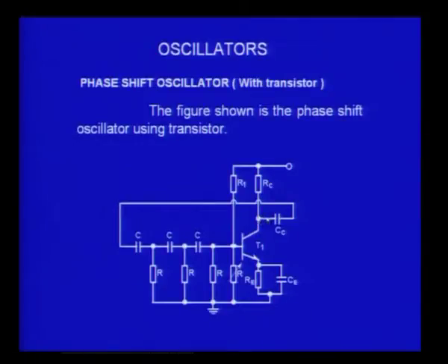Now, what are we doing? We are taking the output, and you see it is brought back through this wire to the input, and at the input what are you doing? You keep on combining a series of RC sets, CR: that output is taken and given to another CR, that output from the R is taken to another CR, and that output is given to the input.